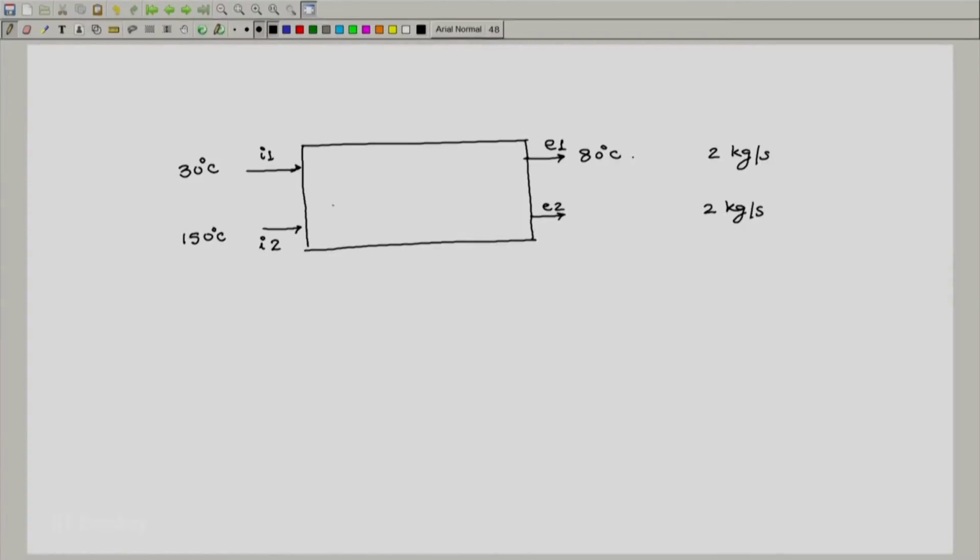A heat exchanger normally is used to exchange heat between two streams, and overall, as far as the outside world is concerned, it is an adiabatic system. That is, we do not want the heat to go elsewhere, it should only get transferred from one stream to another. So, we just show that this is an adiabatic system here and it does no work. We can just write the first law, q dot minus w dot s, and we realize that there are two inlet streams, and in steady state we call this m dot 1 and this m dot 2.